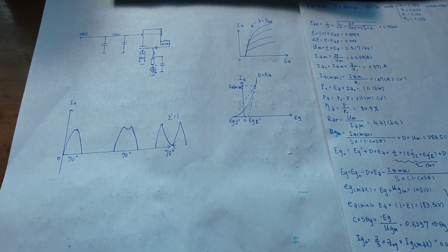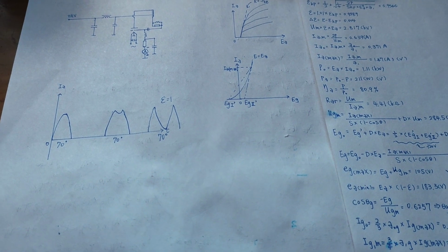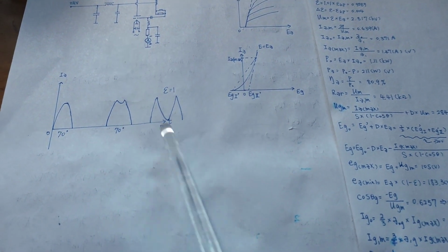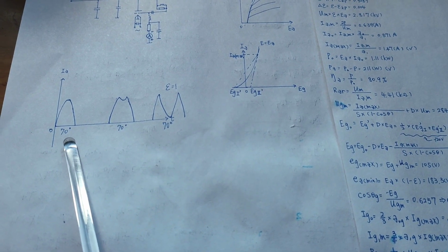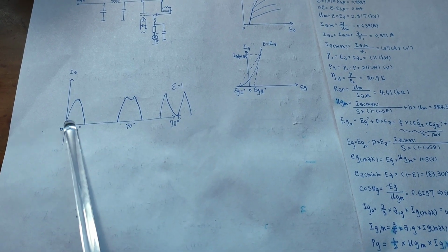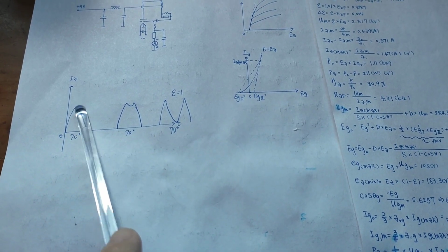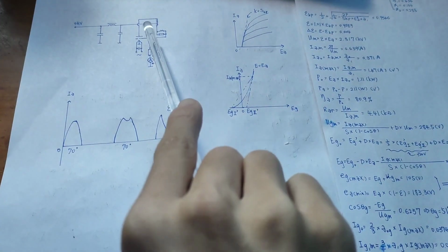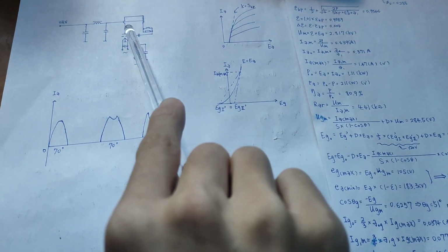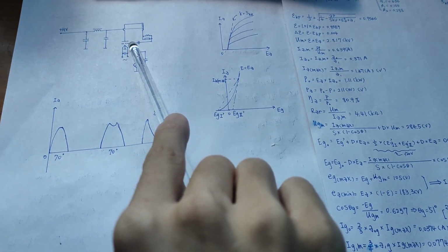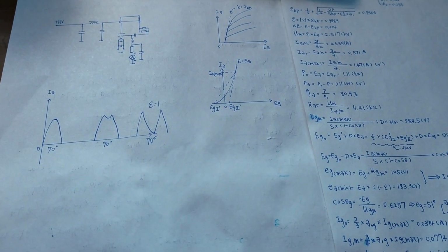And to achieve high efficiency and high power, we need to operate the vacuum tube under Class C mode. Here you can see some anode current waveforms, and the conducting angle is less than 90 degrees, which means the tube is under Class C operation. And to achieve high power in a very short conducting angle, we need a rather higher anode current, which means our grid of the tube will be driven to the positive region. It will have a positive voltage against the ground during some of its operating cycles. So that means our grid current will be larger than in Class A or Class B operation.